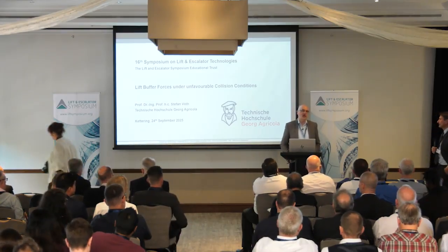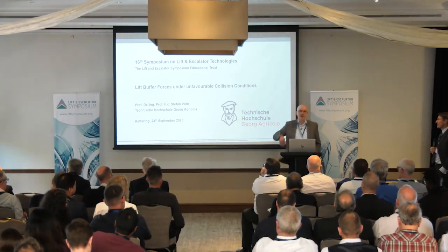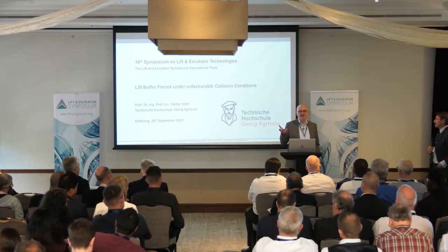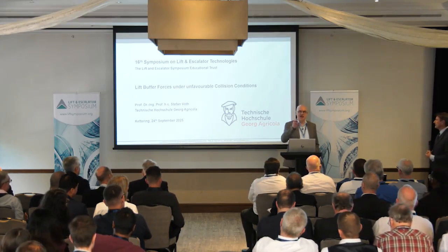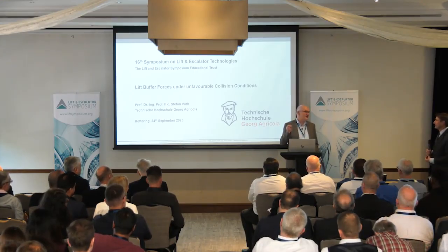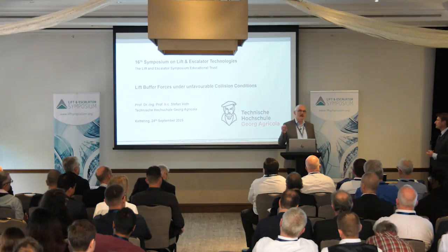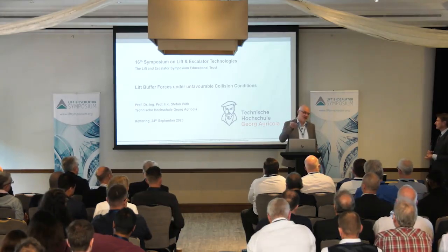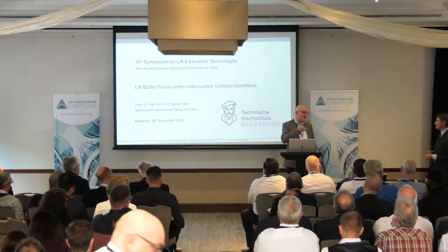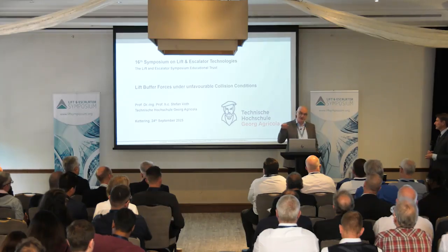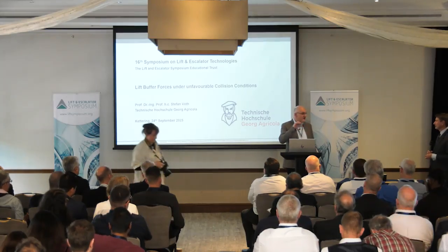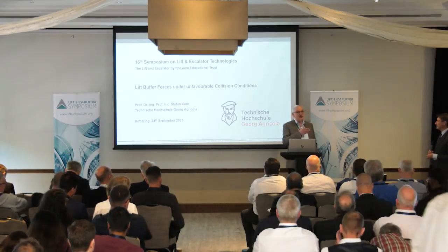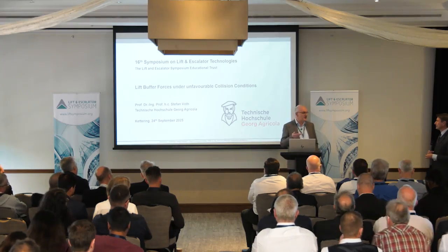Basically, this is just caused by your impact speed. Because if you have a certain buffer design, looking at the mechanics and the hydraulics of the system, just the impact speed decides on the buffer force. And then the mass of your system comes into play, because at a certain force level, this force will induce some deceleration. It just depends on your mass. This is why the different load conditions are of interest.